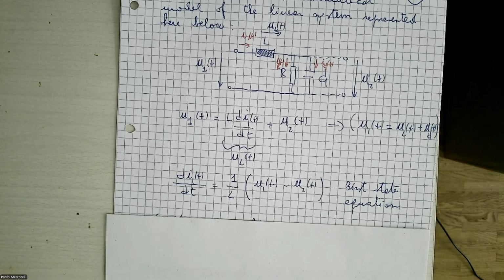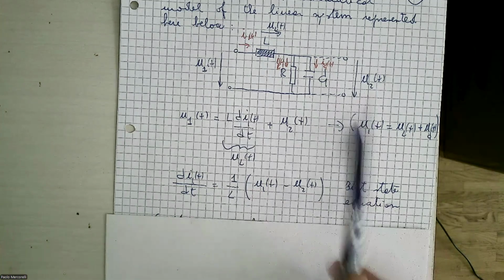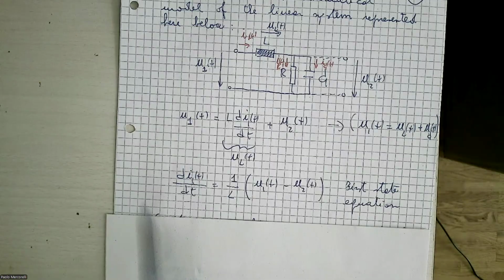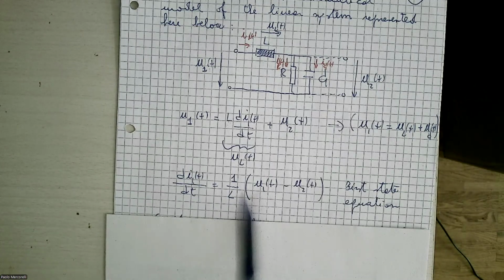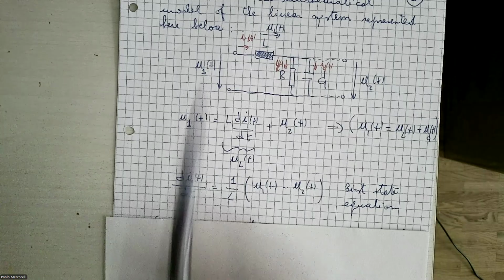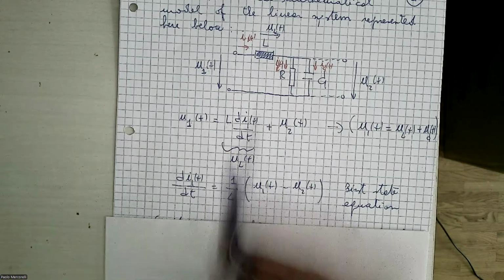Do you remember last time? We had position and velocity. Here we have current in the coil and voltage U2. The variation of the current I1, the voltage, equals something as a function of the input, and of course as a function of the state. Basically, the electromagnetic energy is a function of what I am doing in input and what I have as energy in the system. Of course, it could also depend on the current at this moment in this equation.